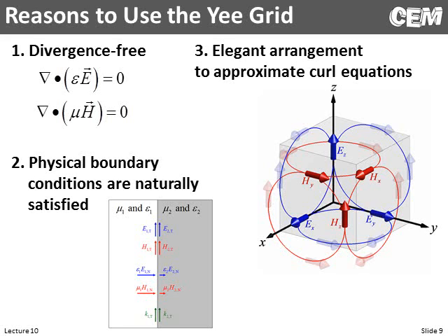And when I first started doing finite difference method, I really had nobody to advise me differently. And I went ahead and did a co-located grid because I thought that was the easiest, most obvious thing to do. And it worked at first. I was just doing 2D simulations, and I moved to a TM polarized wave, and suddenly I was getting 300% reflection and crazy, crazy numbers. And I went through everything. I went through my code, I would say easily hundreds of times, looking for a little sign mistake or something, and everything was always right, always right.